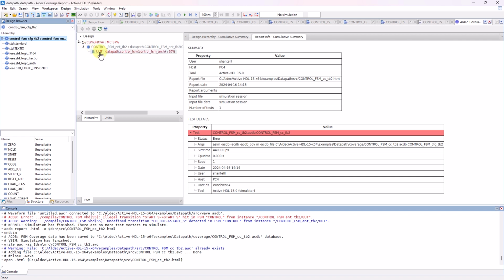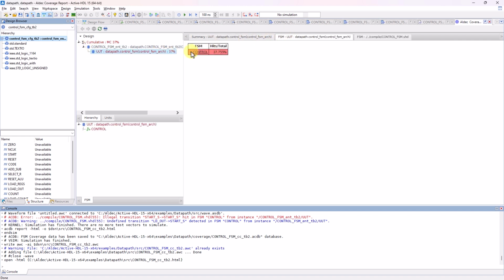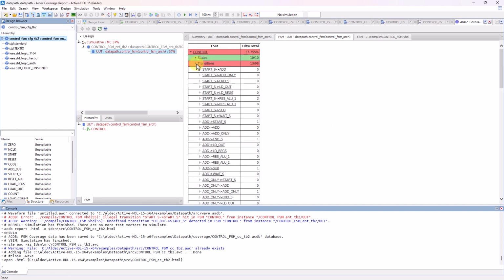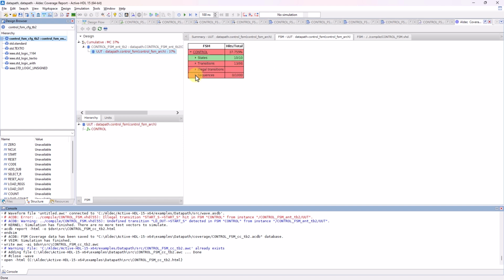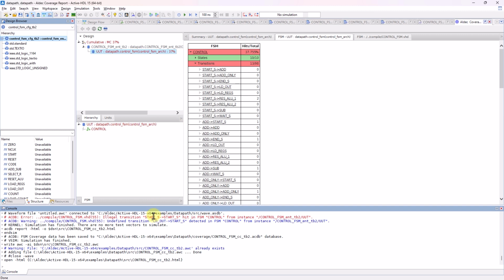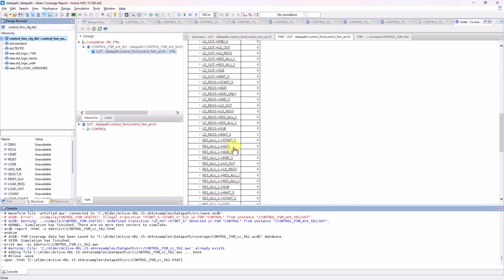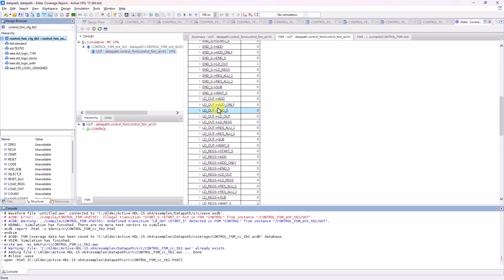Now let's go to the FSM's full coverage. All the states were covered with this strategy, but by defining only excluded components, this strategy barely covered the transitions and didn't hit any of the 1000 sequences. Notice that there's a section for illegal transitions and shows a report that it was hit once, but it's not part of the coverage computation. Illegal states and sequences would have their own section as well if they were defined. And lastly, notice that the undefined transition was detected as seen in the console warning, but it's nowhere to be seen in the coverage report under transitions.